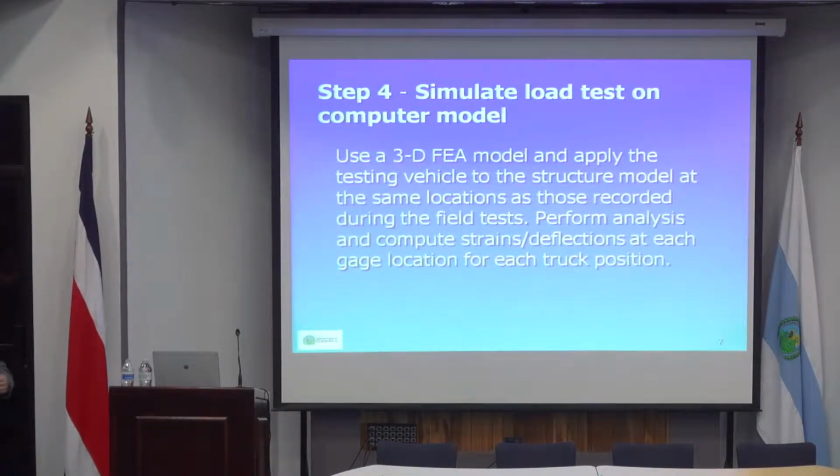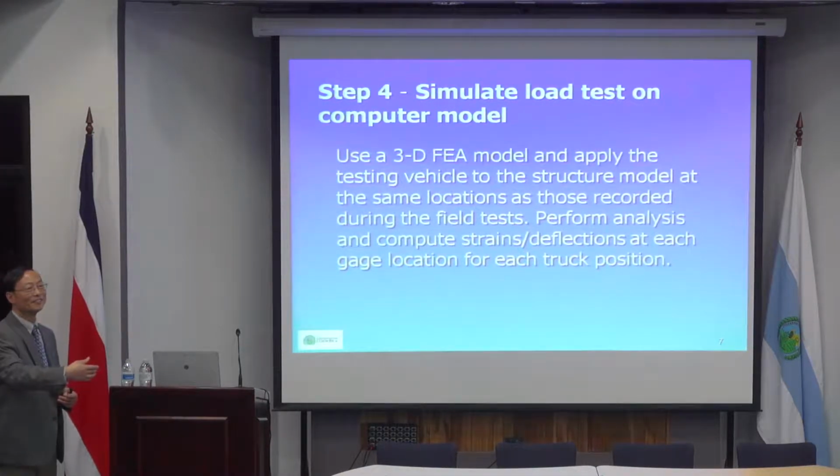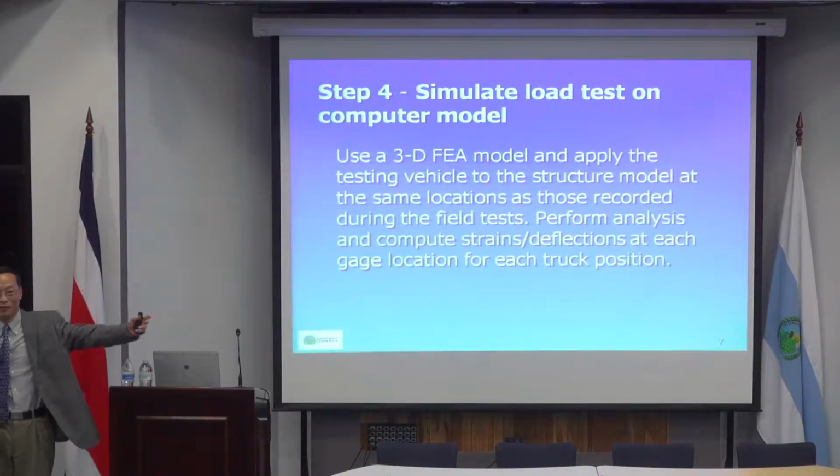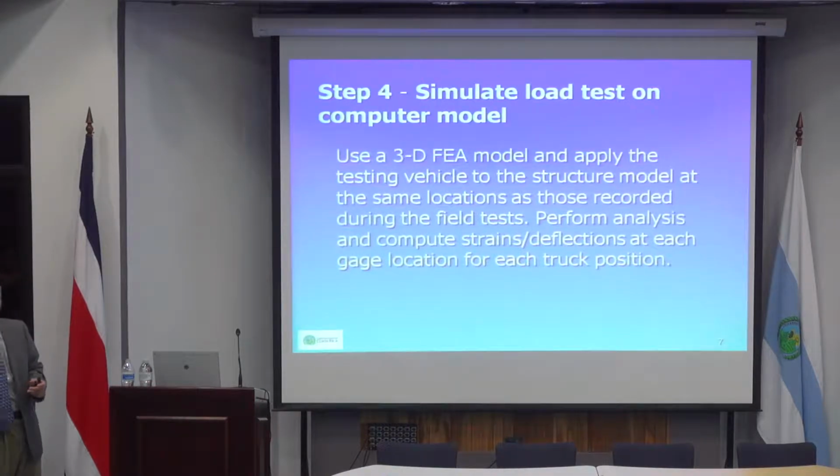By manipulating these, typically you manipulate transverse members. The reason transverse members can be manipulated is that when you do finite element analysis, the longitudinal member is very long. When you cut it into pieces, it does not affect too much.